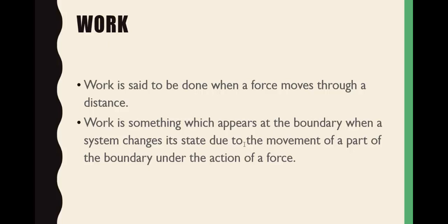So the work done is force times distance, which may also be taken as pressure times area where the boundary is movable, as given in the second part. When you give a force to a solid object, the object will move. When you give a force to a boundary which can create pressure inside the system, the boundary will move under the action of the force, that is, the system volume changes. In that case, the work is taken as pressure times area.